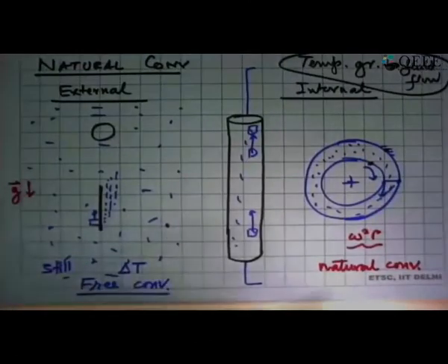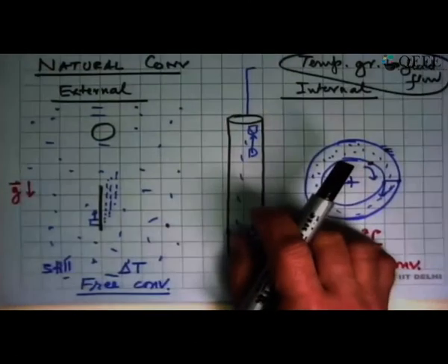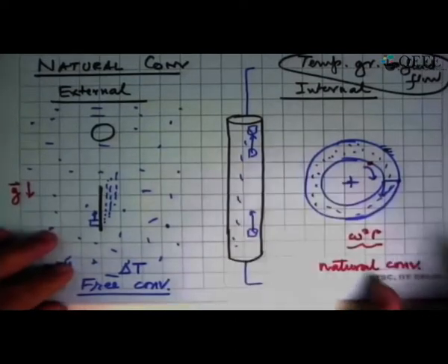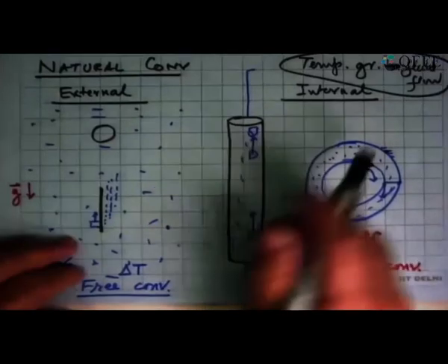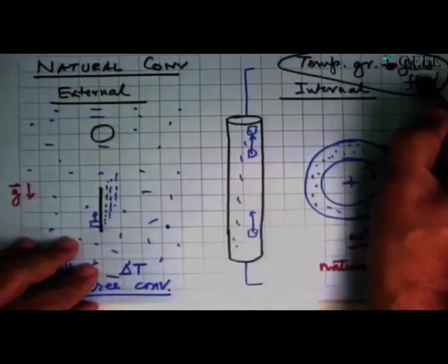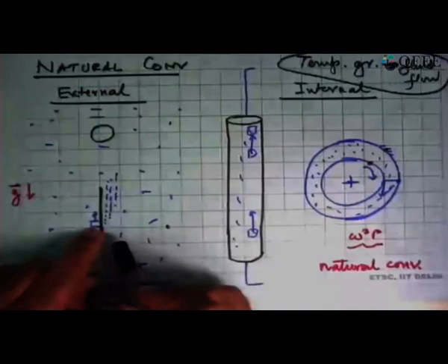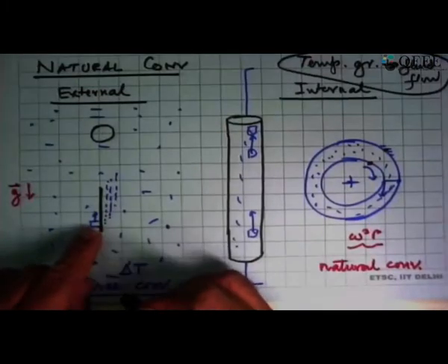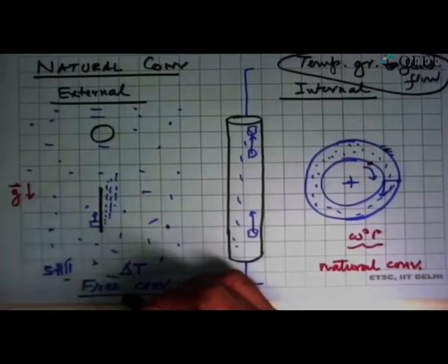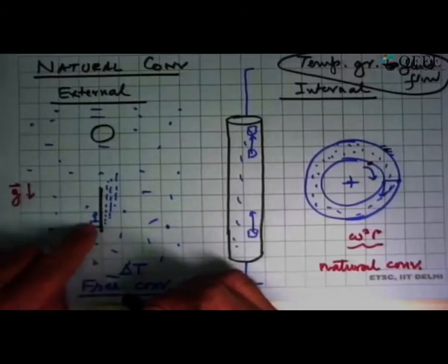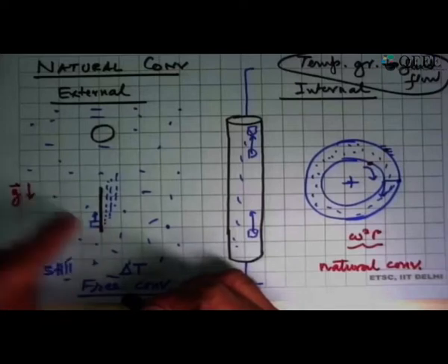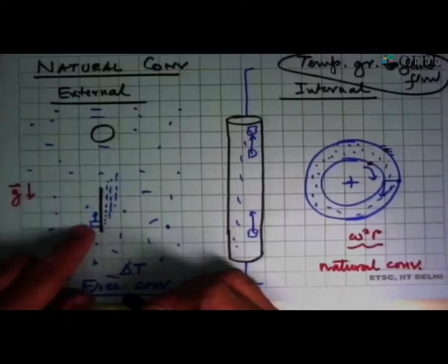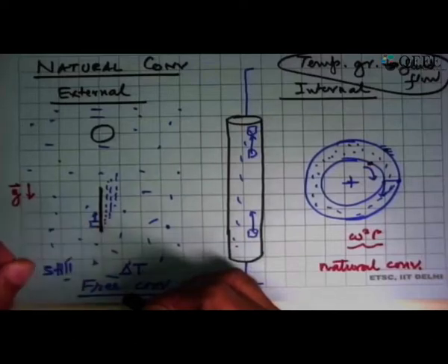And of course, the fluid flow obeys the same laws of conservation of mass and momentum that we had learnt in fluid mechanics. It's the same thing. What it means is that because the temperature gradient is causing a fluid flow, and as we saw here that buoyancy is coming in, we have produced a force on that fluid element, which means that the momentum equation will have this force coming into it, and that force came because of temperature gradient, which means that the momentum equation explicitly has temperature in it.